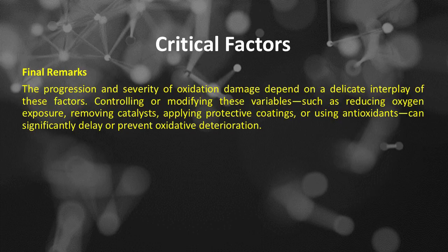Final remarks of oxidation damage mechanisms. Critical factors: the progression and severity of oxidation damage depend on a delicate interplay of these factors. Controlling or modifying these variables, such as reducing oxygen exposure, removing catalysts, applying protective coatings, or using antioxidants, can significantly delay or prevent oxidative deterioration.